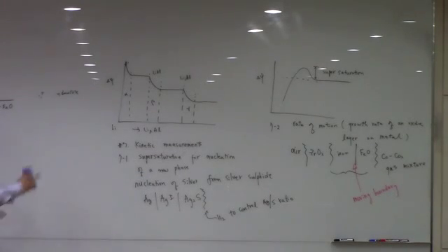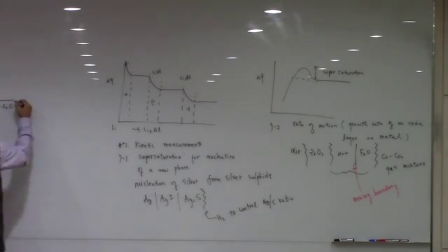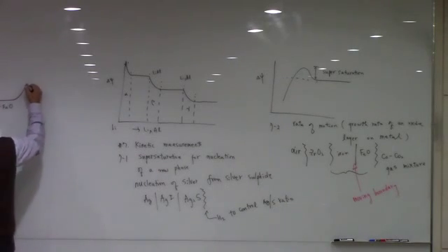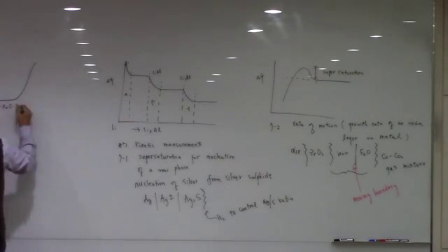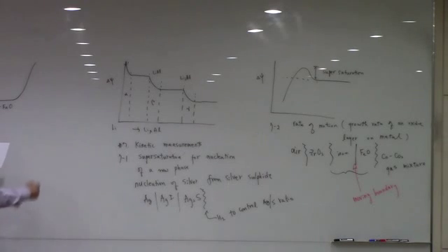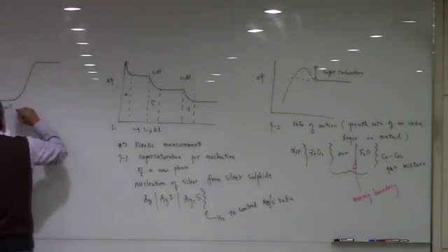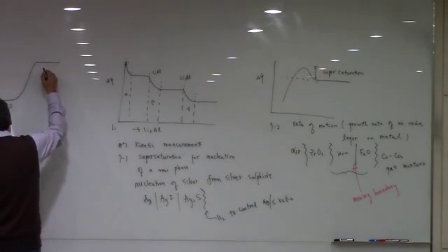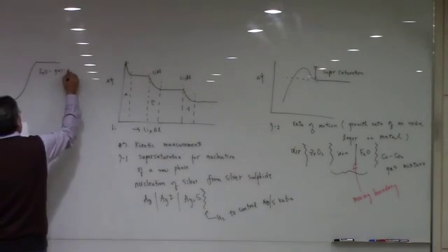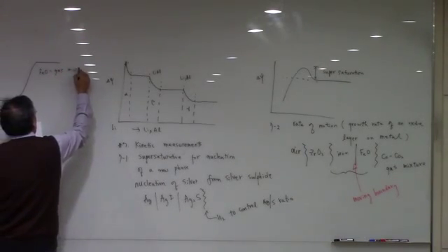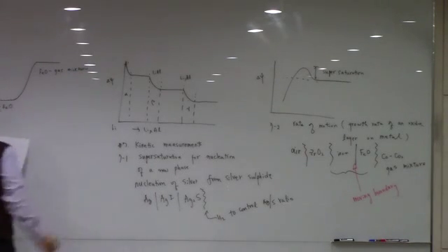And then after everything is turned into the FeO, we have a single-phase region, so that we are going to have another slope here, and then we end up with the plateau again, and this plateau is FeO and the gas mixture equilibrium.